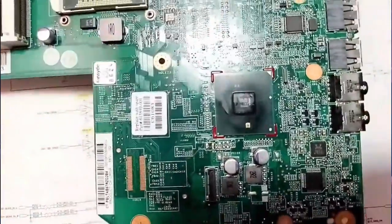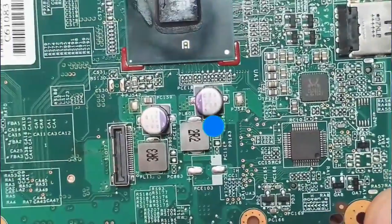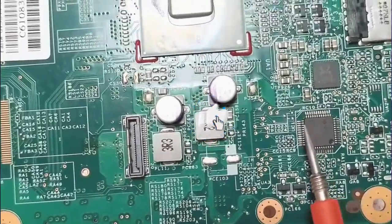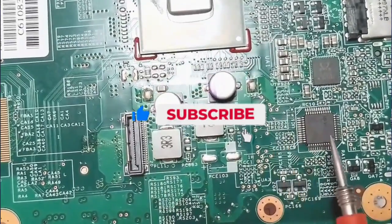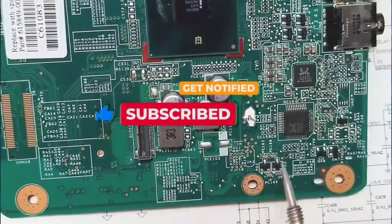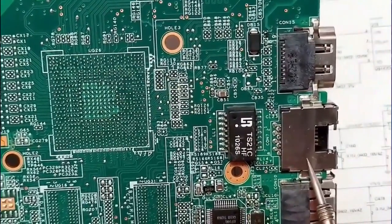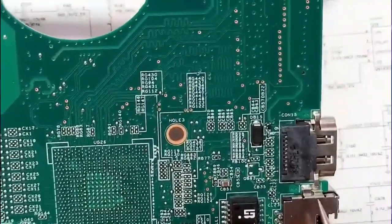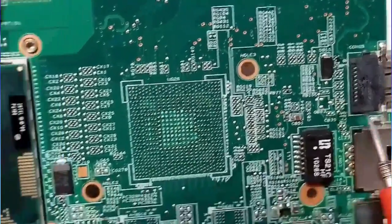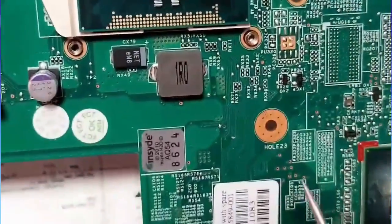Always when you get a motherboard, you should do a visual inspection, okay? By looking at all components in the motherboard, including ICs, capacitors, inductors. This IC basically is the controller for the RJ45. Okay, we have here a crystal oscillator. So over here we have the CPU.